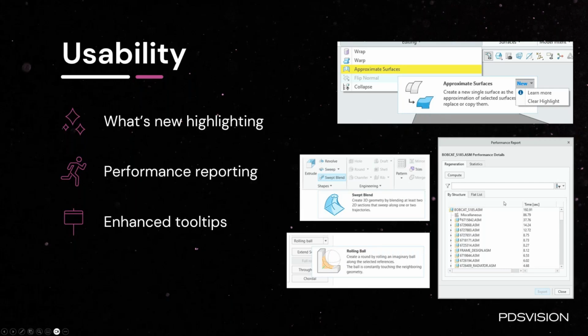If you're struggling with some designs, you've got an assembly or a part that is slow to regenerate, you can use this performance report to run through a regeneration and list out the regeneration times for all of those individual assemblies, sub-assemblies, parts, features, right down to that feature level, and can maybe allow you to go in and optimize your designs. You can find out what's really causing things to bog down and maybe optimize those. So that's seen some improvements in regards to how it presents that information to you as a user.